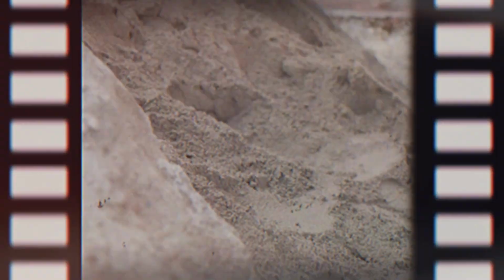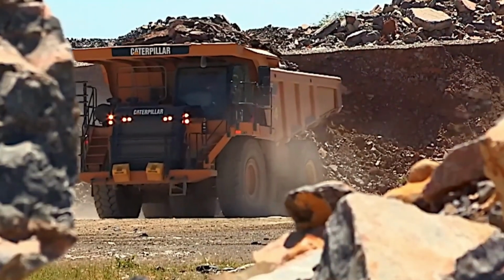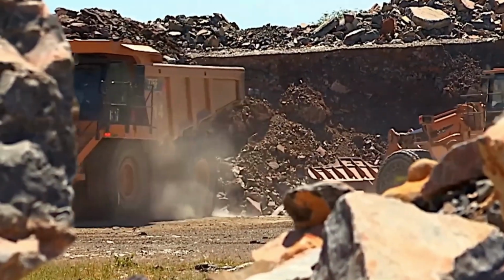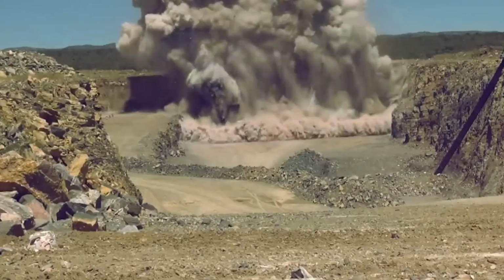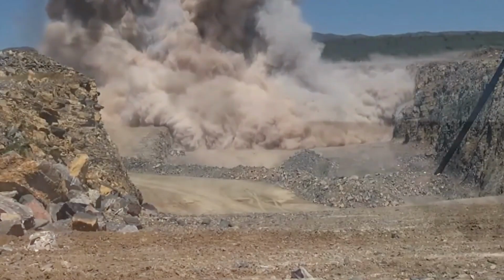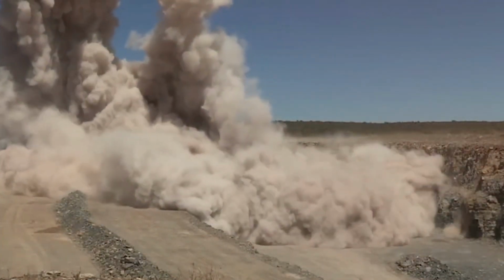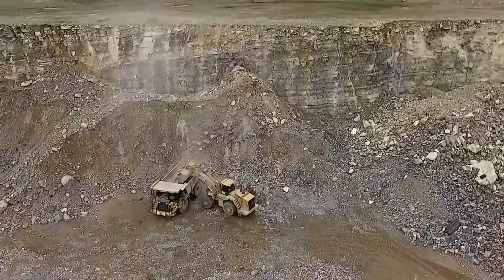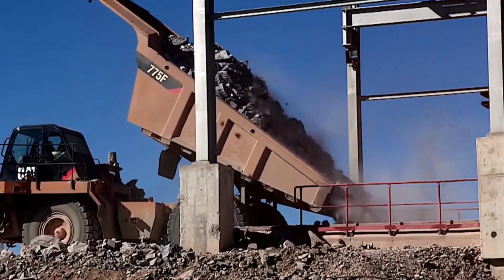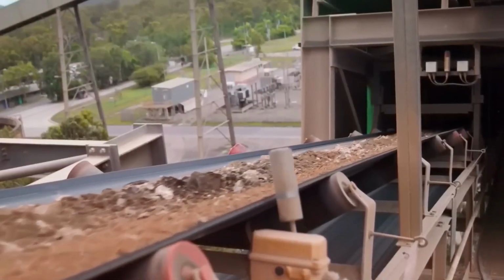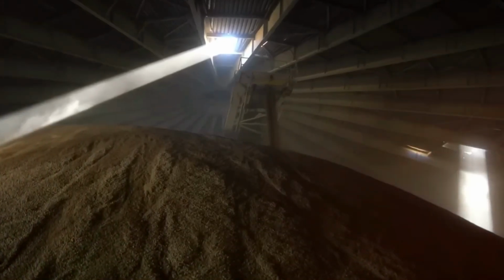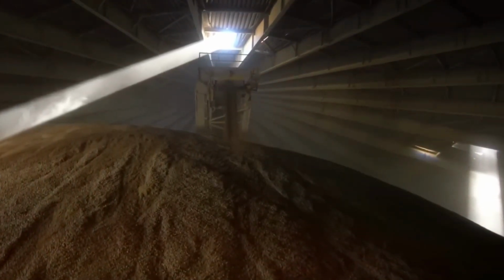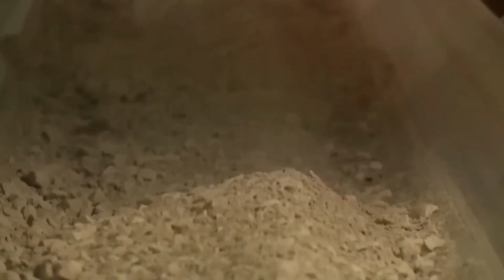Let's begin. The initiation of this complex process involves the extraction of essential raw materials, namely limestone and clay. These materials are often obtained from quarries, employing various methods ranging from controlled explosions to the use of heavy equipment. The ultimate goal is to extract these raw materials from the Earth's crust. Once extracted, the raw materials are transported to a crusher, where they are thoroughly crushed into smaller pieces. The essential follow-up to this crushing process is the careful mixing of crushed limestone and clay in the right proportions, resulting in a raw material.